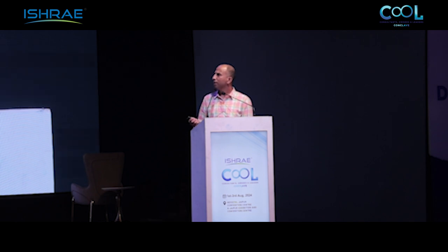Then exhaust recovery, if available, coupled with an absorption or adsorption, is another widely available technology. Solar energy with absorption cooling is another huge technology. The only limitation here is the land area that is required to install the solar collectors. Then indirect direct evaporative cooling, already all of us must know about it. Then deep sea or lake cooling, there are demonstrations of this technology as well, and as I said, this goes with a district cooling kind of setup.